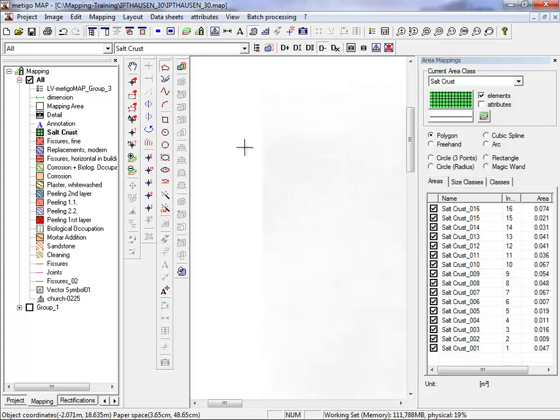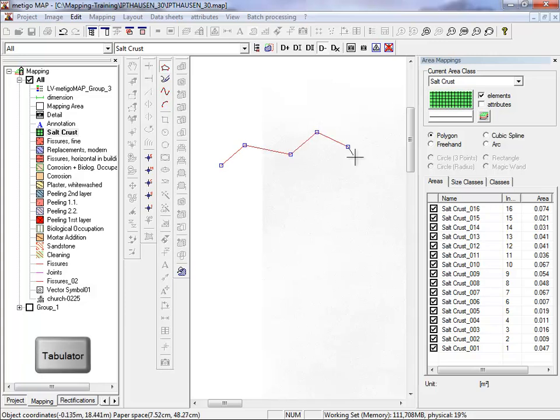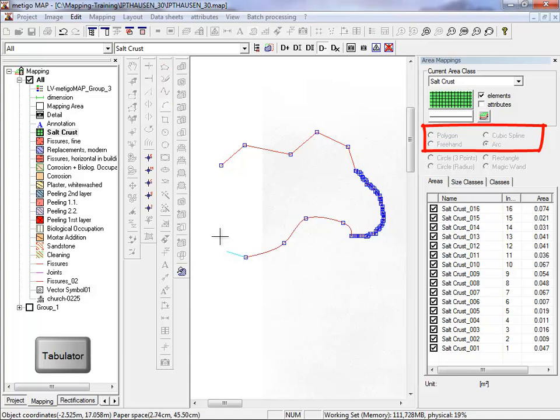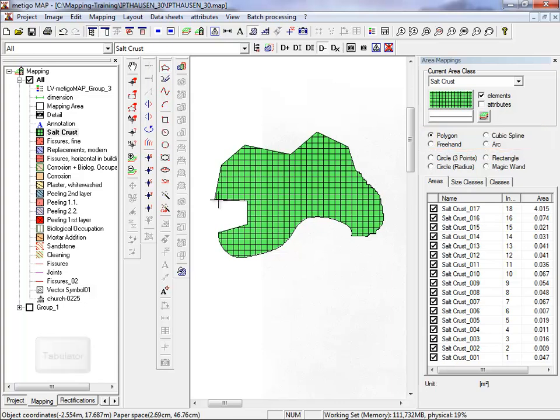The already shown drawing tools can also be combined in one mapping area by pressing the Tab key. We start with polygon, press now the Tab key to switch between the drawing tools, and with every pressing the function jumps to the next. We hold at the freehand line, measure the start point, move the mouse cursor as we please, and press the tabulator key to switch now to the spline tool. Can move on to the arc or skip it, and right mouse click to complete.